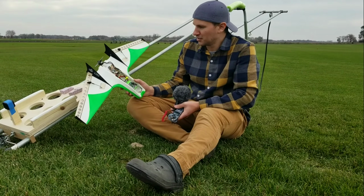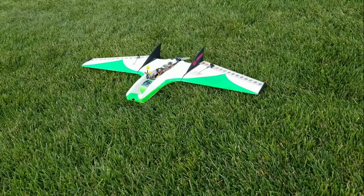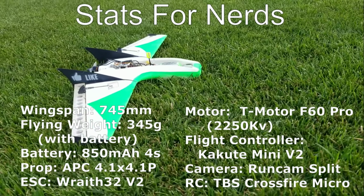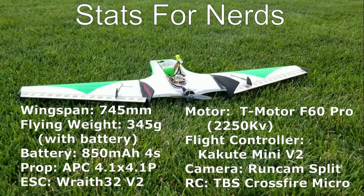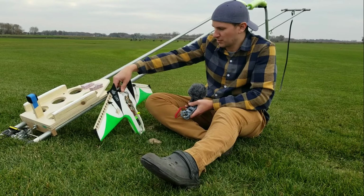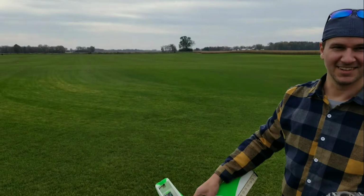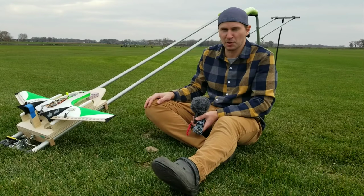We've got a flight controller here today for stability. For power, we're using a 4-cell, spinning an F60 Pro T motor, 2550 kV motor, spinning a 4.1 inch prop. Pretty thrusty feel to it, so I think we should have enough thrust to weight to keep it airborne. And to make sure everything goes smoothly, we've also brought out Mike's catapult because I didn't want to have to whip this by hand today.